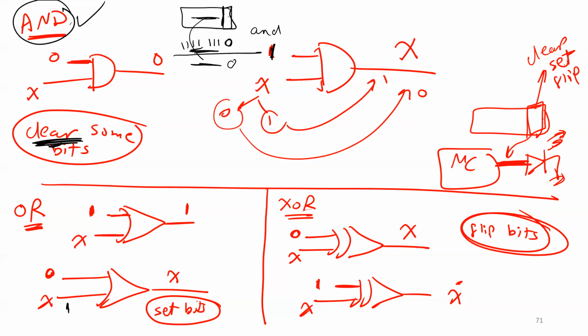Okay, this is number one. How can I use it? Very simple. For the bit or bits you want to clear, I have to put 0 at the location of these bits. For the bits you don't want to change, you have to put ones, because this is how AND works. If you put 1, I'm going to get the same bit again. If you put 0, I'm going to clear it. So here, for example, if I want to clear this bit, I'm going to put 0 here. I don't want to change those other bits, so I'm going to put ones. So 0 AND this bit, I'm going to get 0. With 1, I'm going to get the same bit again, the same bit again, and so on. Any questions?